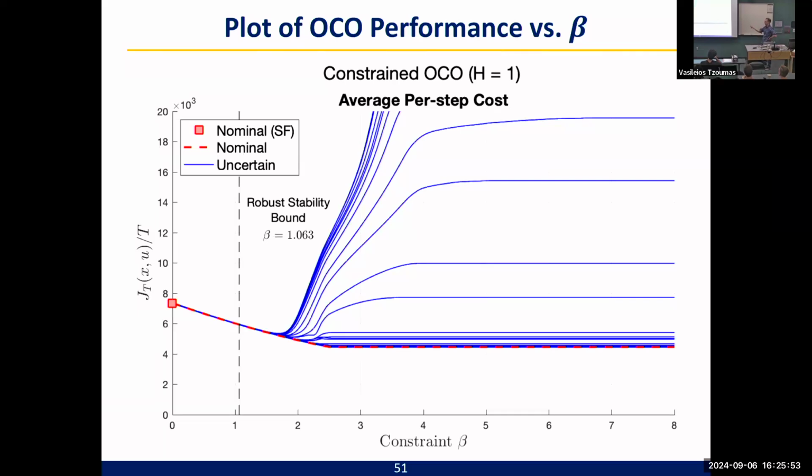Even then, it's still nice that this is a foundational theory. You could think of this beta as like a tuning knob. And you could say, from a practical point of view, I'll start with a small value. As long as it's stable, I'll increase. If it goes unstable, I'll maybe back off a little bit. So it gives some theoretical foundation for why you might want to do that. So that would be my answer. I would say for practical reasons, I agree that this can be conservative.